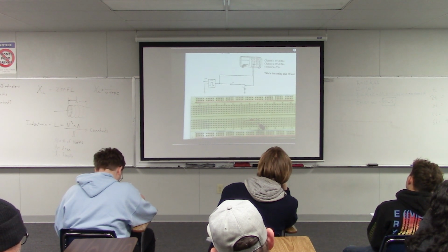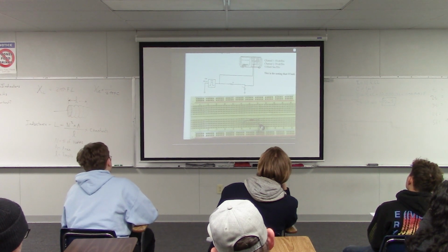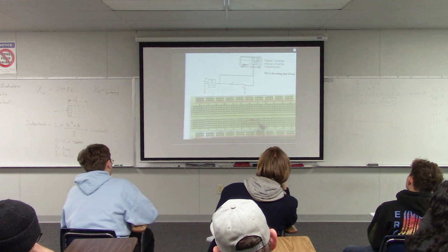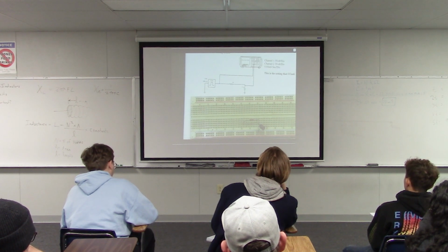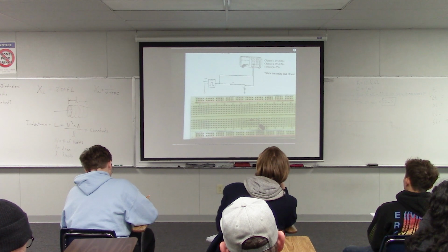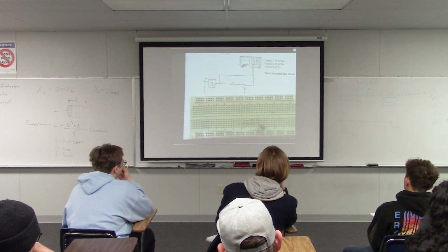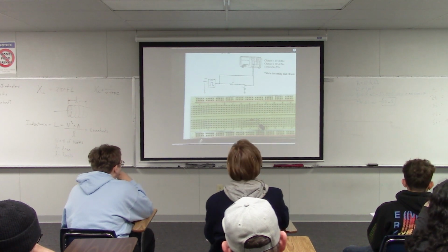So that's what I got. And I'm using this bottom row here as ground because I know that I might have several different signals that have to hook into ground. So when I use this bottom row, I've got all of these holes all along the bottom that I can use for ground.